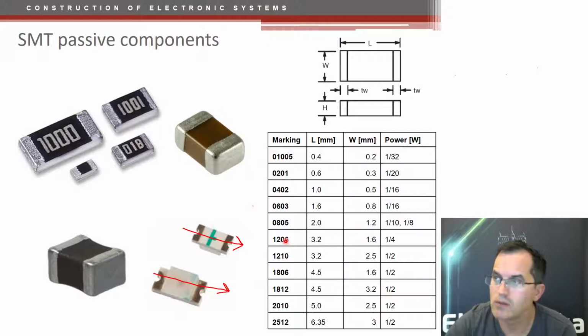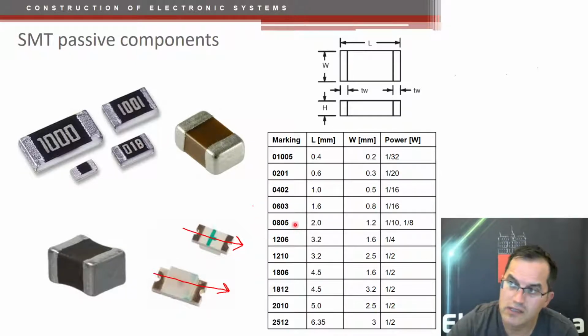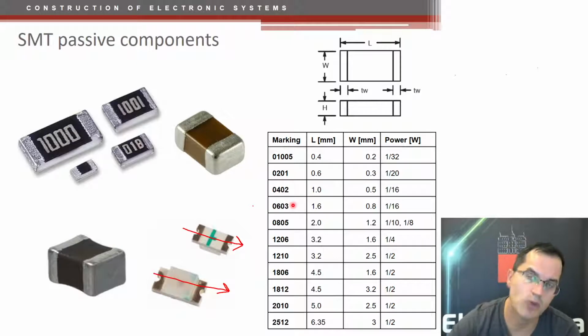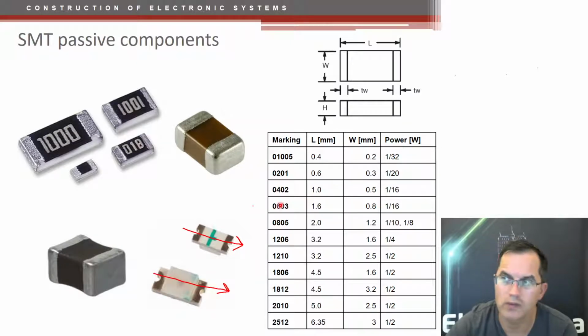The most common sizes we use in everyday life for hobby or prototyping are 0805, 0603, and even 0402 can be soldered manually. Below that, forget it. I would say mainstream now is 0603 for us, because it's still easy to solder and small enough to make some nice small PCBs out of it.